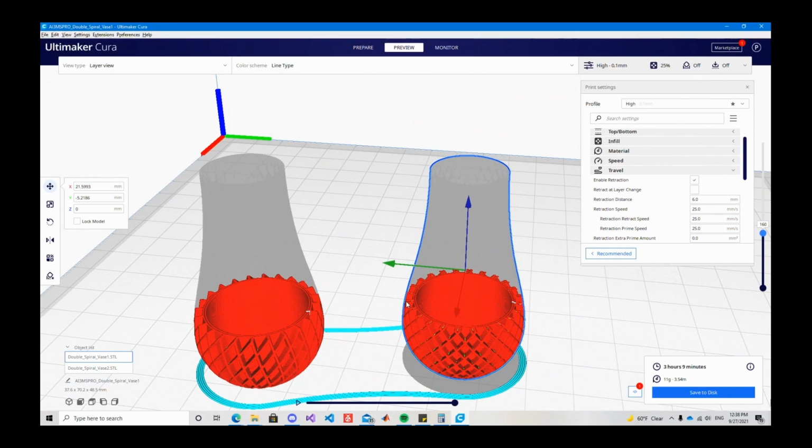And then it's going to create that bridge. So you want the temperature to be in between, for example 190 to 210 degrees Celsius. Around 195 to 200 degrees is normally the best for that, because you don't want the filament to be runny, and so you're gonna have a weird print. Retraction is another way you can solve that.